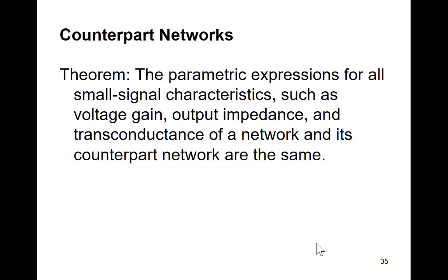Theorem. The parametric expressions for all small signal characteristics, such as voltage gain, output impedance, and transconductance of a network and the counterpart network are the same.